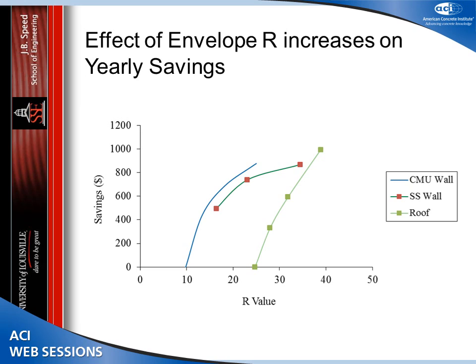This was for a fixed amount of about 28% fenestrations for that building. It's around that. It does vary a little bit. That was the average on a per wall basis. There were some clerestories within the building because we wanted to look at that effect, because most of the newer buildings being designed in the Kentucky area had clerestories.